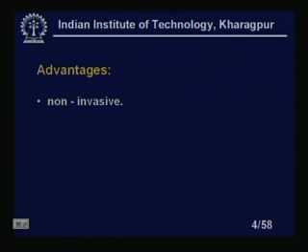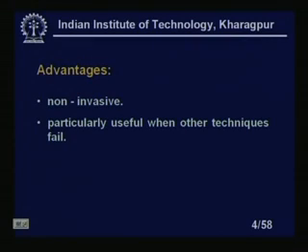Advantages: it is non-invasive. I told you it is a non-invasive technique, right. Particularly useful when other techniques fail. In many situations, we will find that other techniques will fail, because radioactive sources have some hazards, unlike other sources. If you use any other conventional sources, it is fine, but radioactive sources are always associated with some hazard. So, unless it is justified, that means you have to use nucleonic instrumentation, nobody will allow you to use nucleonic sources and detectors.